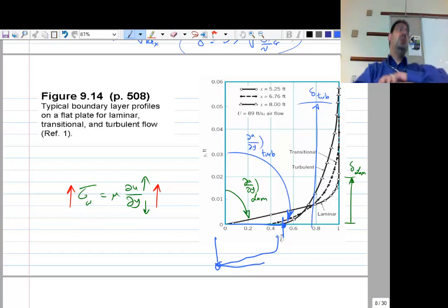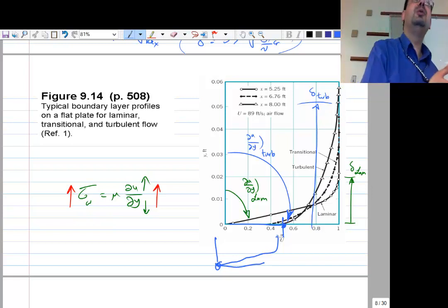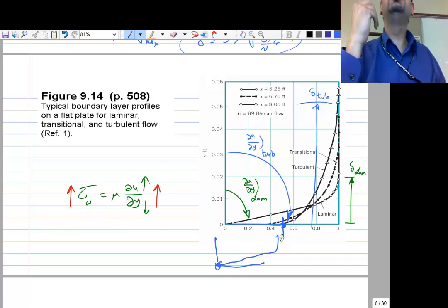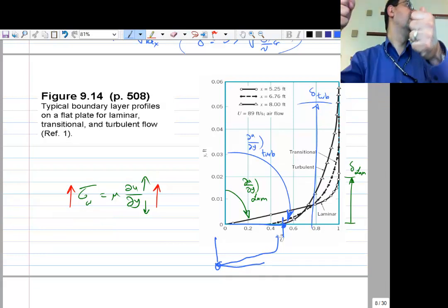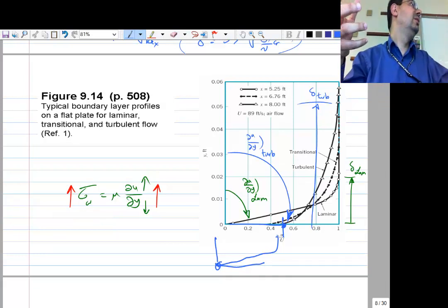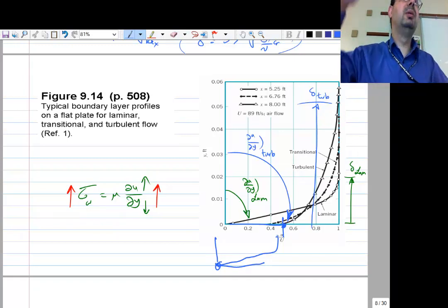And so I remember when I was a student, I couldn't believe what the professor was saying. What do you mean? To become fully turbulent, you make the Reynolds number really, really small by increasing the viscosity, right? It doesn't really make sense, but that's what happens to the velocity profile. It's as if suddenly the viscosity is really high and the flow is just moving as one block, kind of. It really knows everything going on at the bottom and the top.